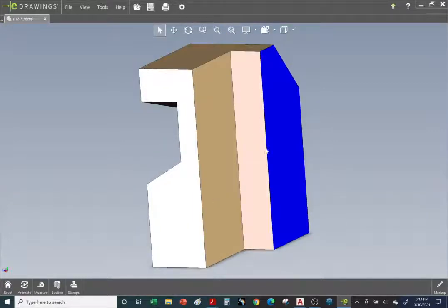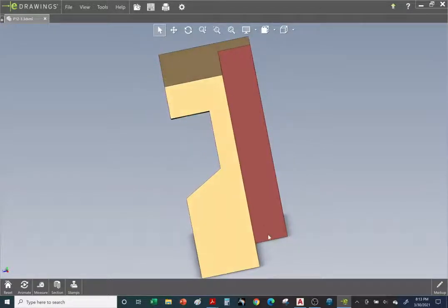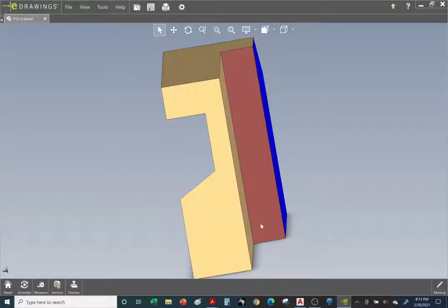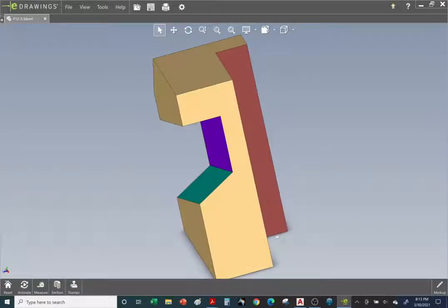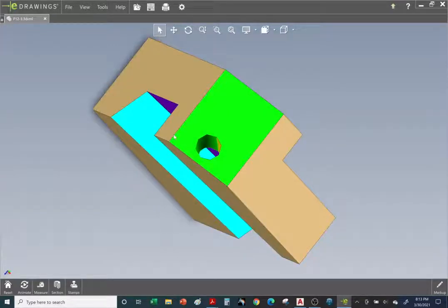Okay, so we're going to go straight down, draw an object line. And from this angle, it's going to look something like this. All right, so this one's going to be a little bit tougher. You know what? Let's first draw the red hidden lines. This is a little confusing. Let's do the red hidden lines first. So we need a red hidden line for this edge and for this one. Then we'll take care of the object lines.